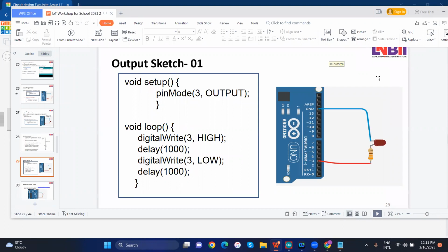Then you can remove that board and connect it again. For the serial port error, remove your board from the USB and connect it again. Then it's working.